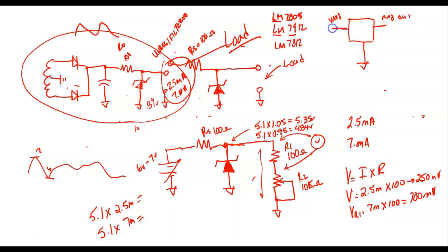And then, of course, it recommends that we come up here and put some pre-filters and post-filters in, but they give you the size. These are not your filter capacitors. And we're through with the design. So if this had a 7805, then this right here would be a 5-volt regulator.